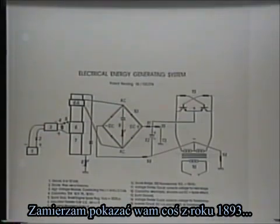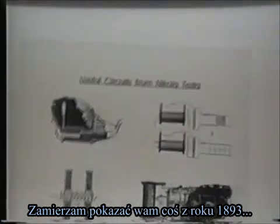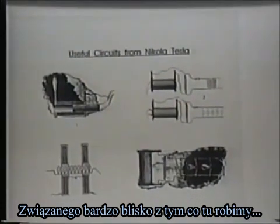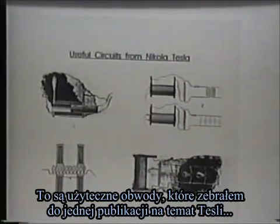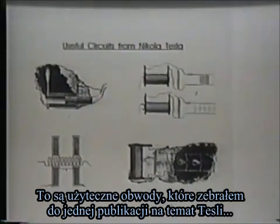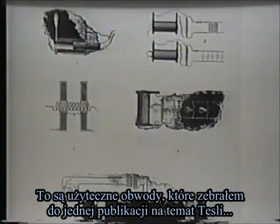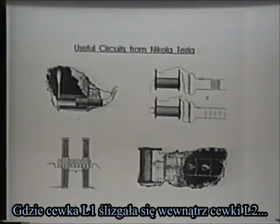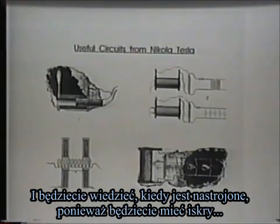And I'm going to show you something from 1893 that relates very closely to what we're doing here. These are useful circuits which I gathered up out of one of the Tesla publications. If you notice, number 1 there is showing that tuning circuit which I showed you early on, where we slide the L1 coil inside the L2 coil, and you know when you've got it tuned because you start getting sparks.